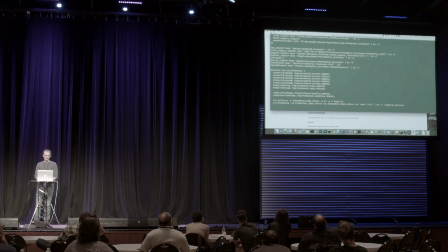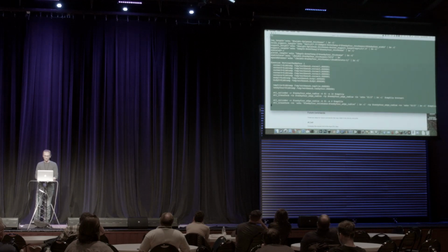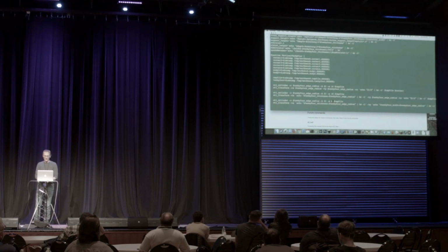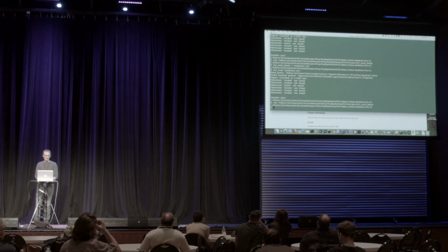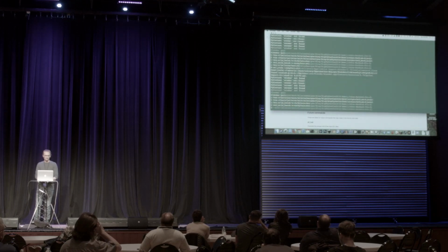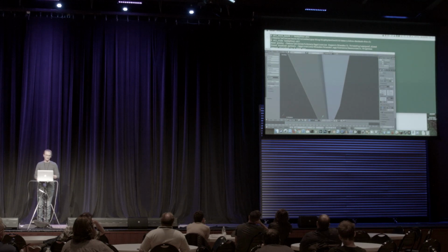So the STL cylinder command here has this -s option where you can specify how many segments to approximate a cylinder. So that's set to 4, so instead of a cylinder, it's actually just a rectangular solid. So let's make this like 16. So there's 4 corners, so I'm changing it. We'll run this again. And there, now we have a pretty nicely rounded edge instead of a chamfer.